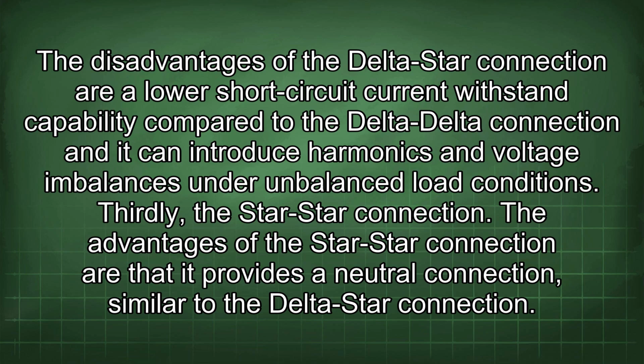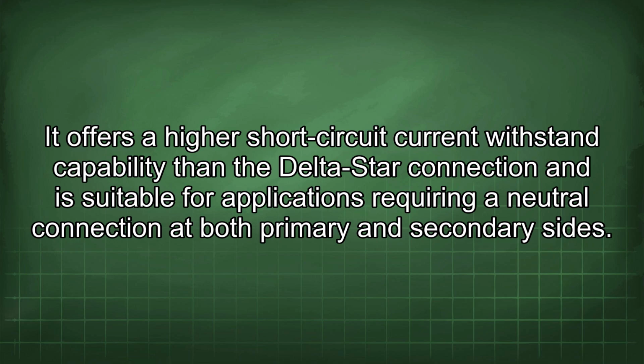Thirdly, the star-star connection. The advantages of the star-star connection are that it provides a neutral connection similar to the delta-star connection. It offers a higher short-circuit current withstand capability than the delta-star connection and is suitable for applications requiring a neutral connection at both primary and secondary sides.